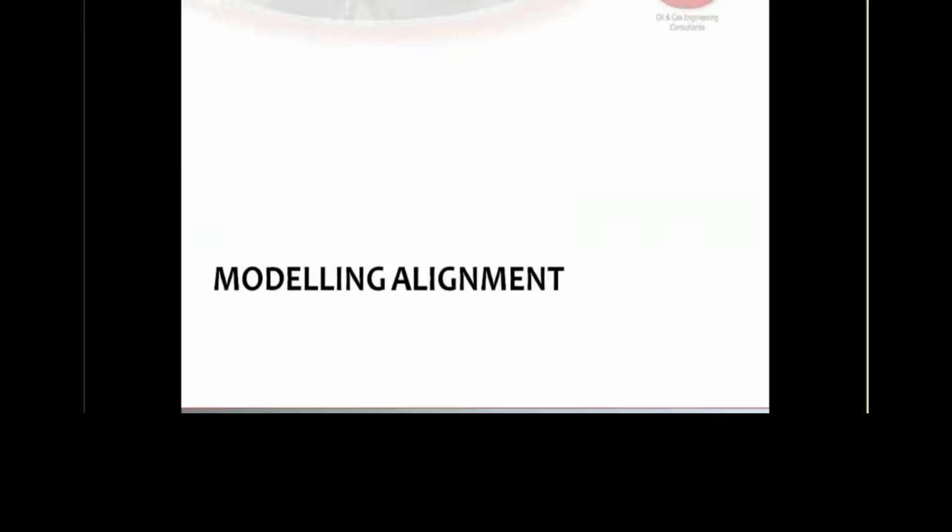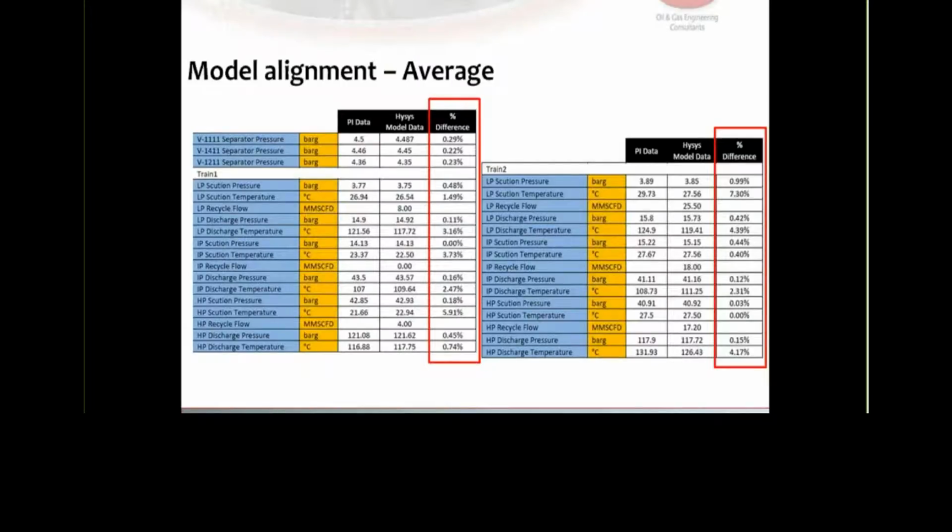So now that is all good. So we have all that information that we got. Now this is what we are going to use to actually build a picture for ourselves and to better understand and align to what the operation is, like what the system is doing in real life. So what we did is we took the real data. We obtained the data from Pi, and then we compared it, without taking the assumptions that we made, through these data. We built our HYSYS model, and we compared the data against each other.